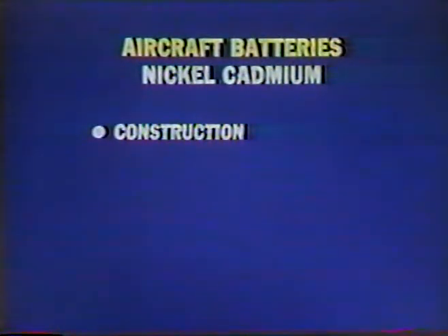Nickel-cadmium construction. The base of the NiCad battery is its plate material or plaque. Powdered nickel is fused or sintered to a fine mesh nickel screen to form an extremely porous material. The positive plate plaque is impregnated with nickel hydroxide. The negative plate plaque is impregnated with cadmium hydroxide.